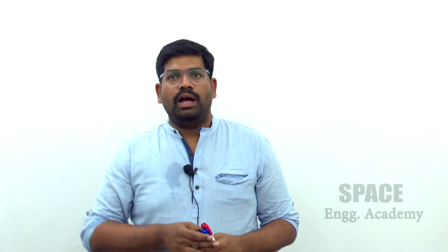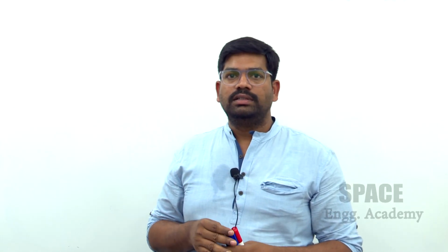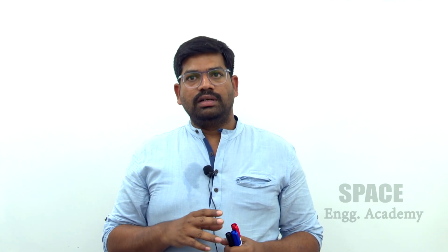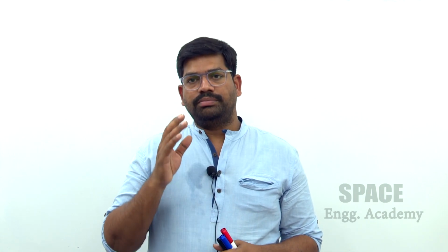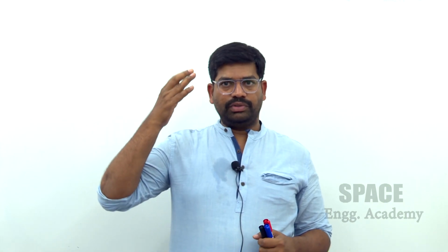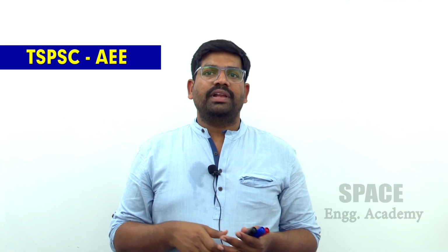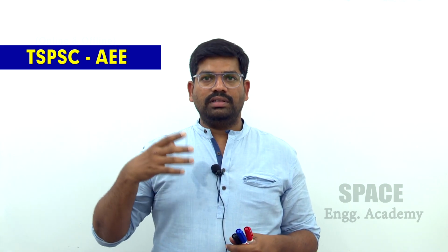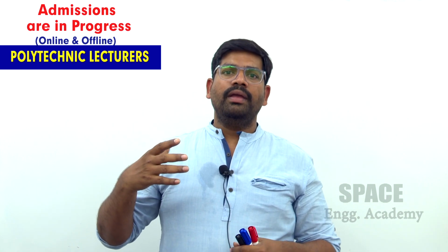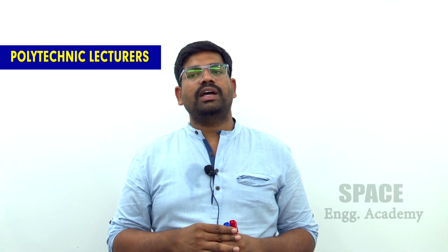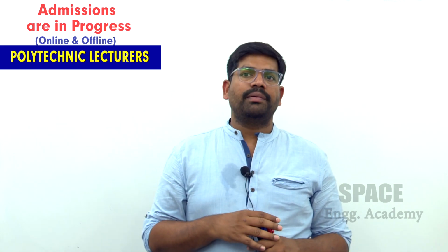Right. Up to now we had seen the different kinds of errors associated with our PMMC instrument and how to compensate those errors. If you look at these errors, like frictional error, frequency error, hysteresis, stray magnetic field error and temperature error, all these are the errors we discussed. Other than these errors, what are the other possibilities of errors associated with our PMMC?